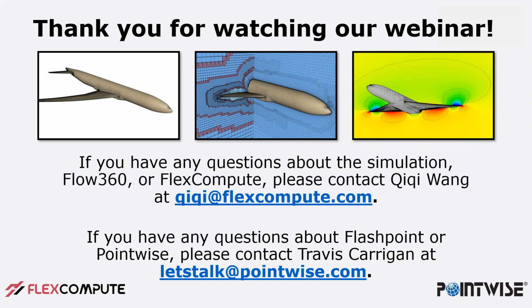Another question about quilts, being merged and what's the best quilting strategy. Again, really just making sure that quilt boundaries are aligned with curved boundaries like a wing leading edge, or a hard concave or convex boundary like a wing root or a trailing edge. You don't want quilts spanning these types of feature edges, and you'll have your best results with that.